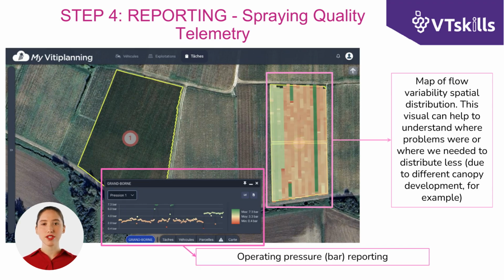By comparing the flow rate with the operating pressure recorded during operation, the opposite trend between pressure and flow rate can be seen, that is, maximum pressure, minimum flow. In the continuous red line, a deliberate obstruction of the machinery was generated to simulate a malfunction that reduced the flow rate and increased the pressure.